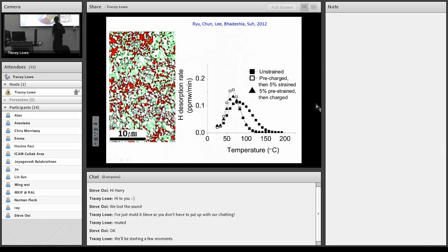So that's a very interesting fact that yes, you want the hydrogen to end up in the austenite because it's a strong trap. But then if you do something to trip the austenite, then you're basically providing an internal source of hydrogen to the ferrite. Not a good thing.